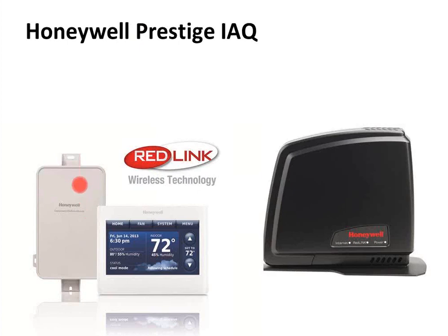So the nice thing about this stat is that I only need 2 wires going through the wall, and chances are I always have 2 wires. Even if I had someone who had a heating only system and they're now adding cooling, they still had a 2-wire Honeywell thermostat on the wall. Most people have 4 or 5 wires, but even if they only had 2, this guy would work. So he's kind of nice in that regard.